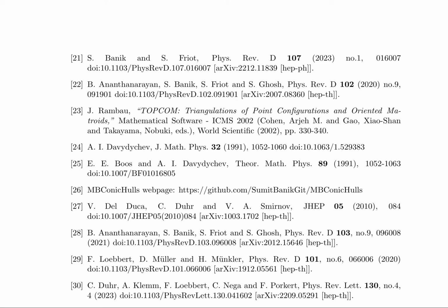The following section presents a detailed overview of the mathematical framework underlying the proposed methodology. Specifically, it outlines the fundamental equations governing the dynamics of the system, including the Navier-Stokes equations, the continuity equation, and the energy equation. These equations are discretized using the finite element method, which is employed to approximate the solution of the nonlinear partial differential equations. The authors also introduce a novel stabilization technique, termed the streamline upwind Petrov-Galerkin (SUPG) method, to mitigate the effects of numerical oscillations and ensure stability of the numerical solution.